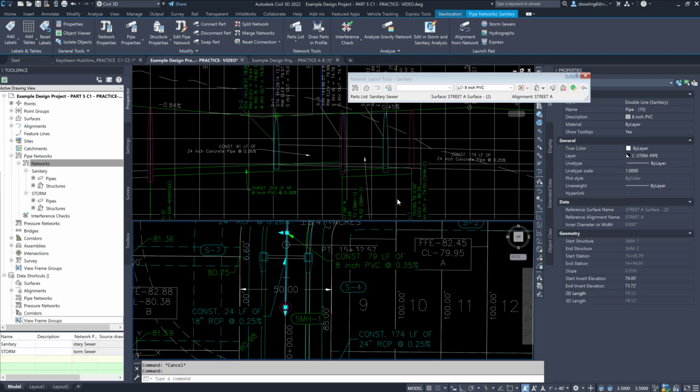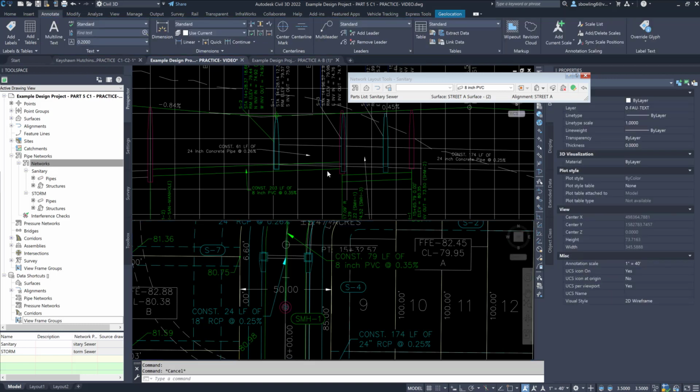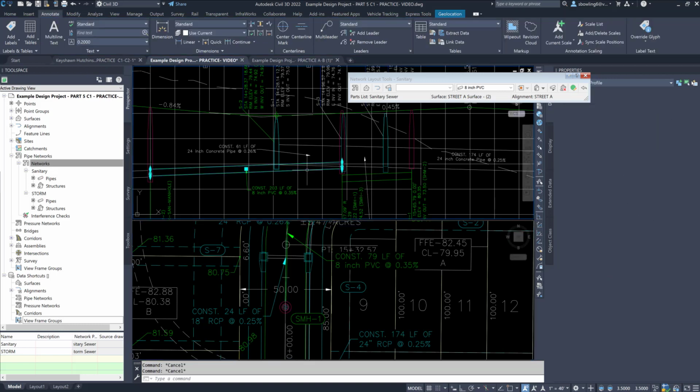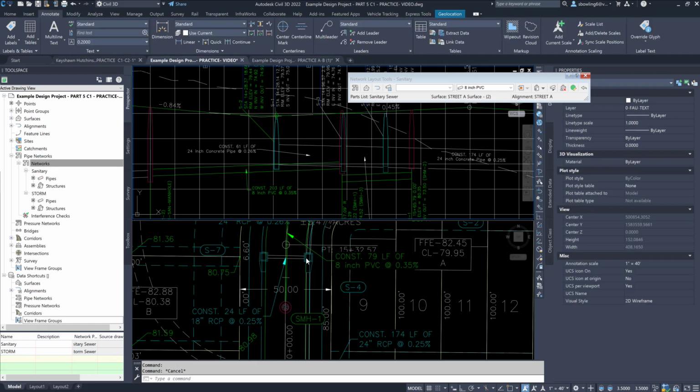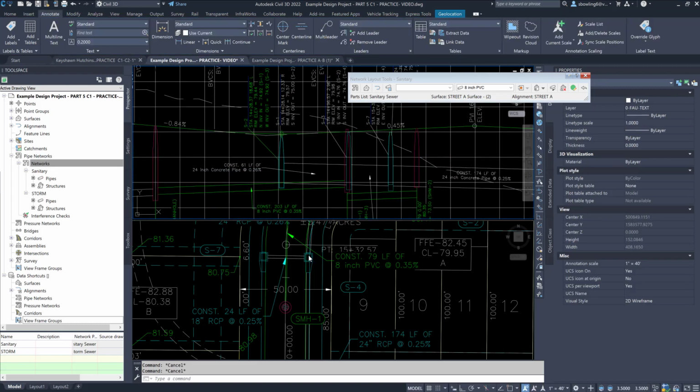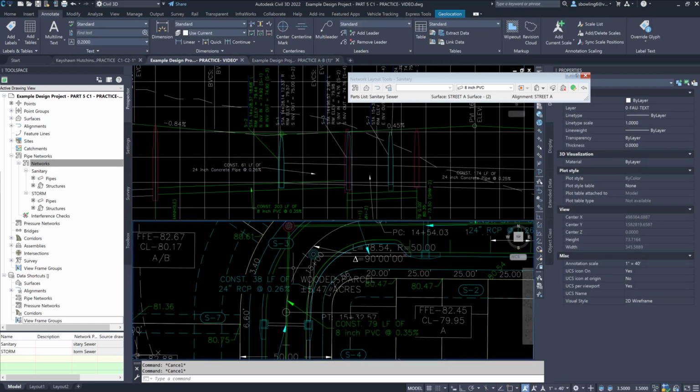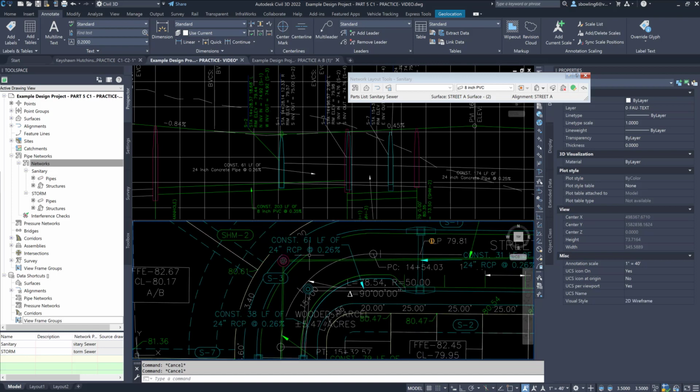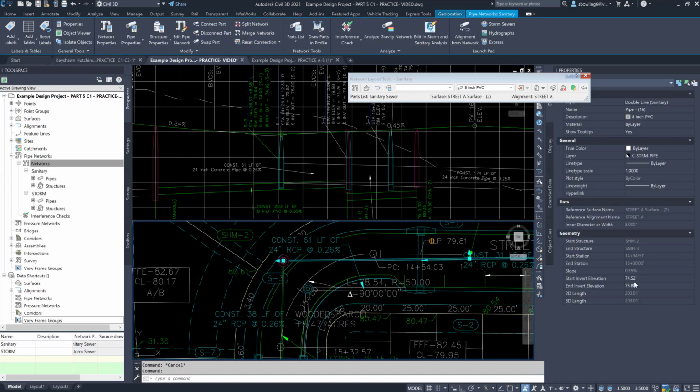Okay. That's not enough, so I'm going to drop it another half. So go 73.5 and 73.22. I still got my 3%. Now I've got plenty of room underneath there. So I'm dropping it a foot, this one 1.5 feet. That means I have to touch them in plan view. So there's my first one. So I'm going to drop that 1.5 feet.